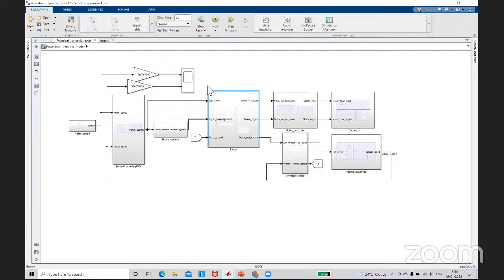If you want to do the performance analysis with the quadratic approach, you will require the acceleration data, which you have to collect from real-time testing, or which is already available, like acceleration drive cycles. Again, those will depend on your different vehicles.